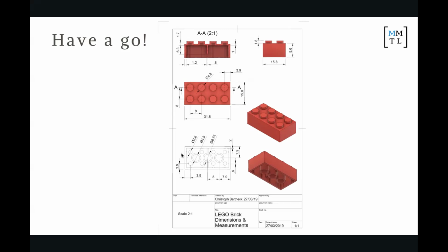And then those parts on either side of the cylinder, again, just extruding all from that face on the inside here. And then the final thing was to create those little small divots on the inside of the block. And this was just sketching each one of them and then mirroring it across to get all of them. It didn't let me pattern them, I think, but yeah, that's how I did it.